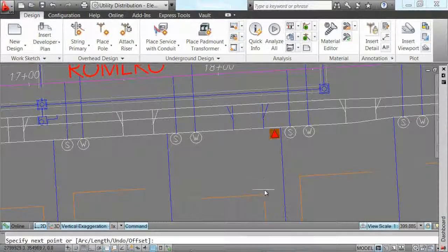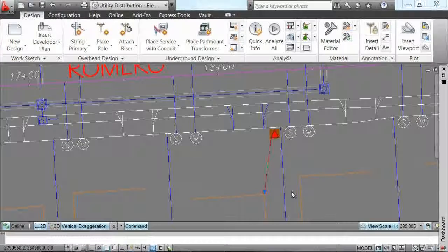Also note that when I touch my underground service to the individual transformer, the tooltip will actually identify what I'm connected to, in this case, the actual transformer. Very important as I'm establishing the actual connectivity for the electrical model between the transformer and the electric conductor.